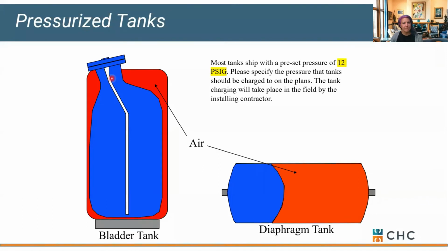And the last one I'll throw at you is we have guys who want to install a bladder tank on its side, okay? And yes, you can do that. So this expansion tank, the one on the left here, you could rotate it off to the left because the system connection would be at the lowest spot in the tank. The thing you can't do is rotate this tank to the right, because now picture this collar being elevated in the tank. It would put a lot of stress or strain on the internal bag. Okay, so yeah, really good question. We can certainly help troubleshoot if that's the case.